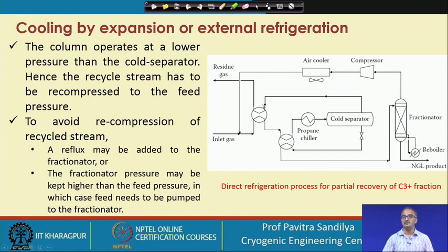So in either case, whether we are going to recompress the gas or compress the inlet gas will depend on the particular situation at hand, that is, at what pressure the inlet feed is available. Accordingly we have to decide whether we shall be going for compression over here or compression over here. So it is a typical situation we have shown here, where we are recompressing the vapor from the fractionator.